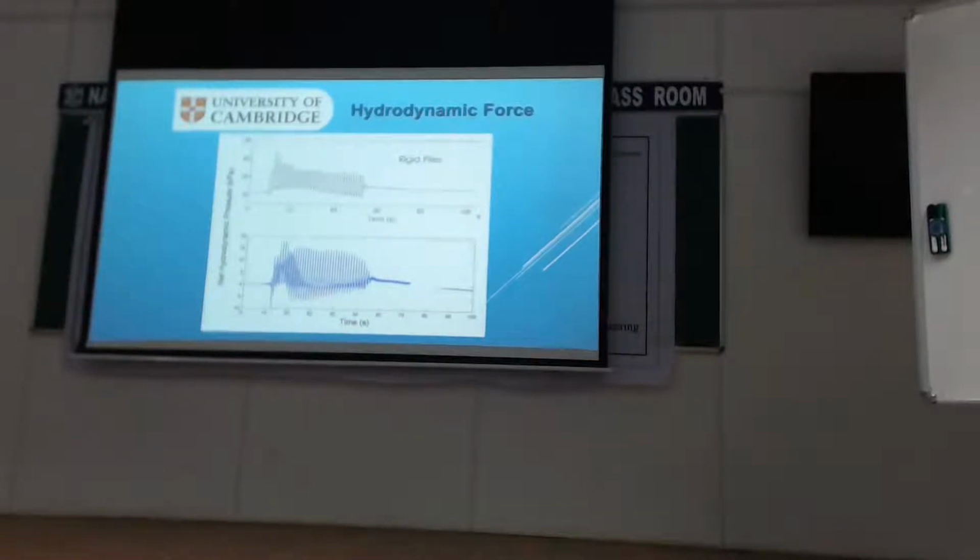And for rigid piles also, firstly, the pattern changes, but the sizes are bigger. You'd expect them to be bigger for a rigid pile because it's not going anywhere. It'll attract more force. That's a given. So now the axis go up to 40 kPa here.